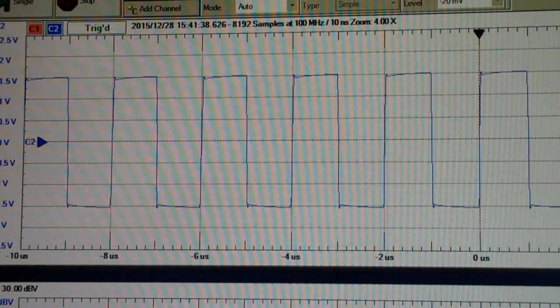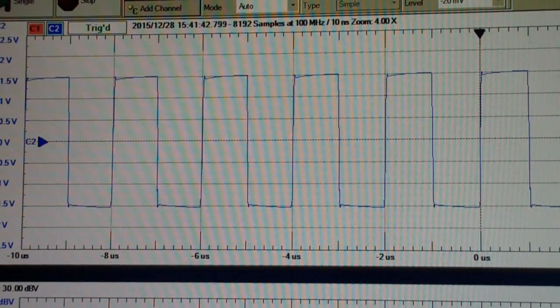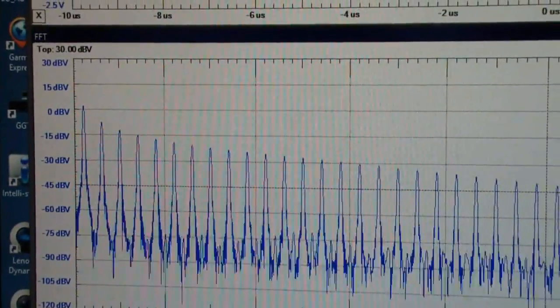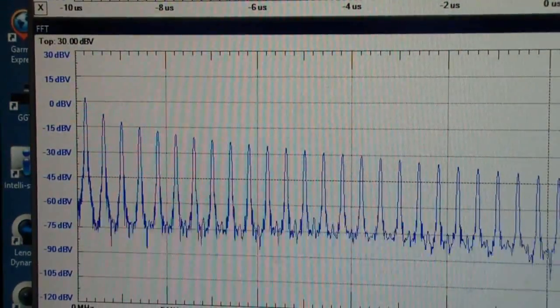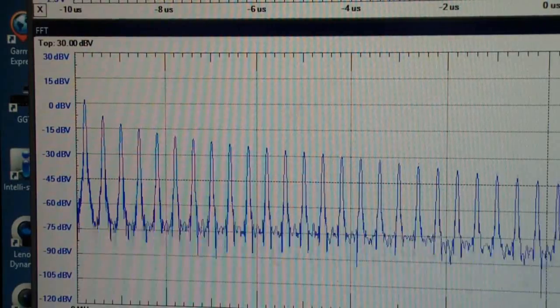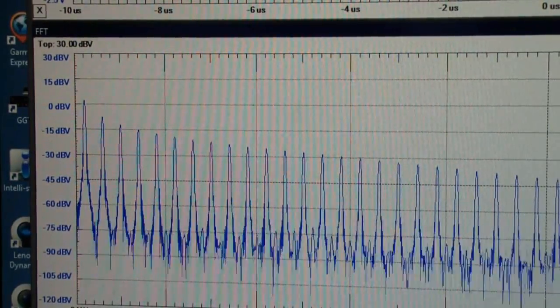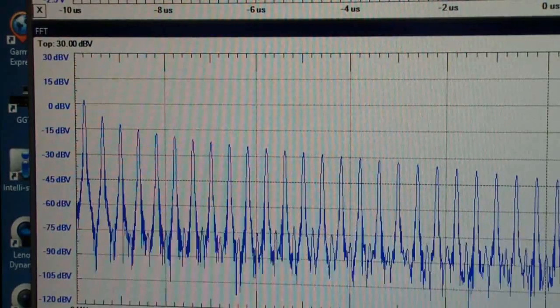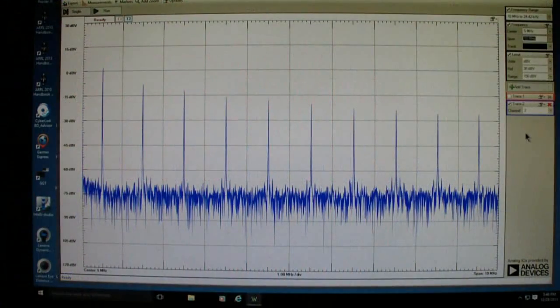It's taking that signal and it is actually doing a mathematical transform. That is, it's computing frequency components from the sample points. Now what I'm going to do is switch and show you the spectrum analyzer capability in the analog discovery. Now I've got the spectrum analyzer connected.